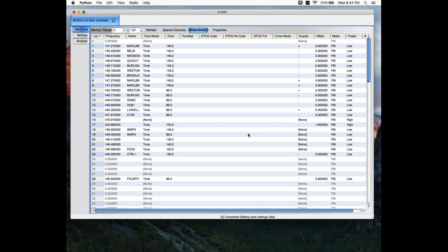I can tell you my own story from cabling between a rig and a computer, not necessarily programming, but it was actually CW keying on a K3. If you use the wrong chipset, you end up with a really chopped off signal on your transmitted CW, and it all came down to just the right chipset. So if you're not making your own, just do a little snooping around, and you'll probably find somebody that had the exact same problem you did and had found a different cable that would work. Also, if you're going from a serial port to a USB with one of those adapters, that also can be another problem point.